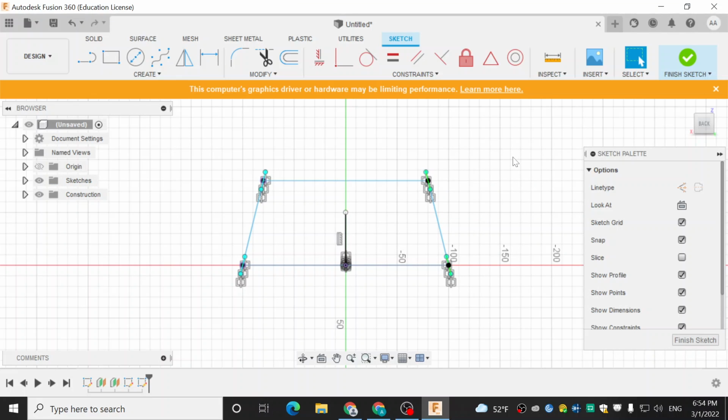Cool. So, first thing that we're going to do is we're going to grab this top green dot on this top line here. What's going to happen is if you grab that green dot and you try to drag it to the right so that it's vertical, parallel with the vertical axis, it is going to bend the spline line that you have.